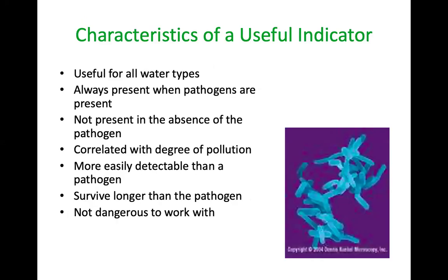Now, E. coli is used because it is useful for all water types. E. coli are present when other pathogens are present. They're also absent if other pathogens are absent, and it gives a correlation or degree of pollution, and is more easily detectable than pathogens. They can survive longer than pathogens, and they are not dangerous to work with.